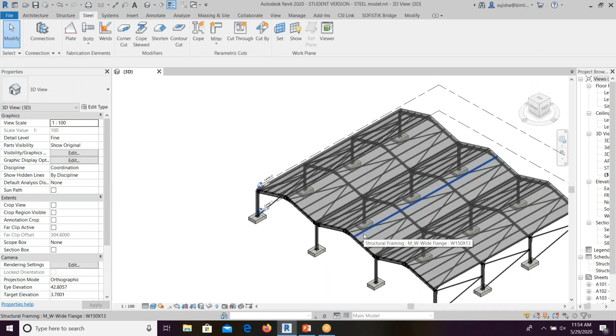In concrete you need to change the dimensions, but in steel there is no need to change the dimensions when you consider the frame sections. Why? Because according to the code itself, it is set in the family. So you can just pick that one. You can also take the concrete quantities of beams, columns, slabs and everything. I forgot to show that one.